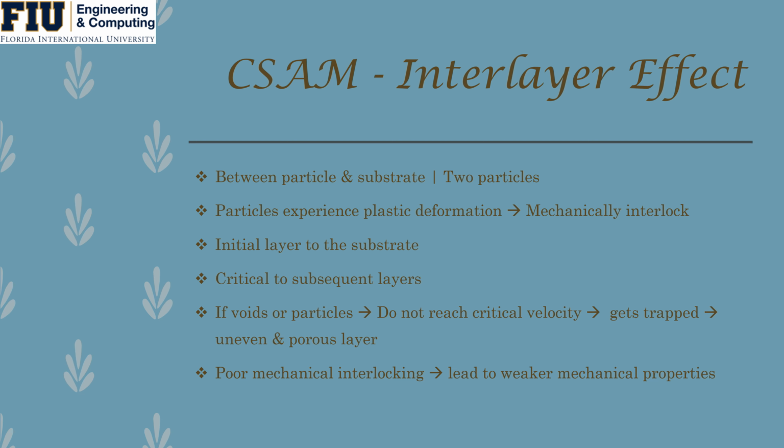If porosity occurs in the initial layer or the subsequent layers, this will allow further subsequent layers to also incorporate porosity. This will lead to poor mechanical interlocking as well as poor mechanical properties overall.